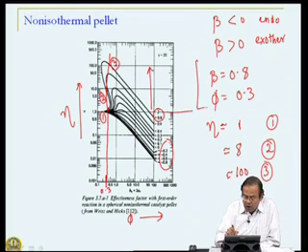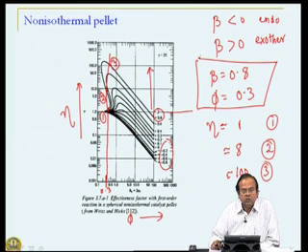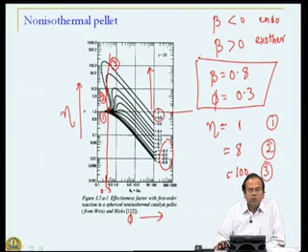So, for the same value of reaction conditions, I could in principle have 3 different values of steady states, a behavior which is characterized by multiple steady states. Everything else is the same, it is the same catalyst pellet, the properties of the catalyst pellet are the same, my Thiele modulus or diffusional resistances, whatever it is, is the same, the reaction, heat of reaction, everything is the same.